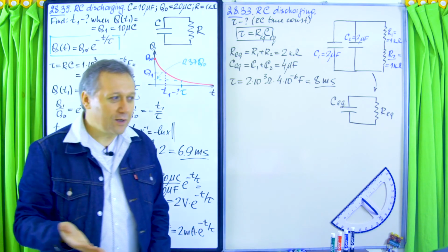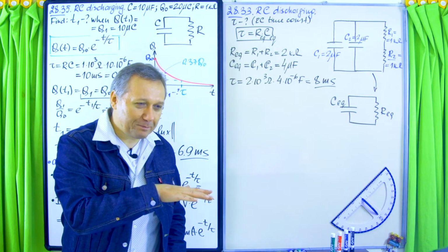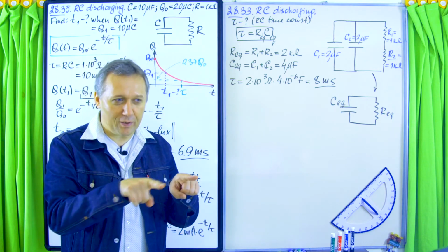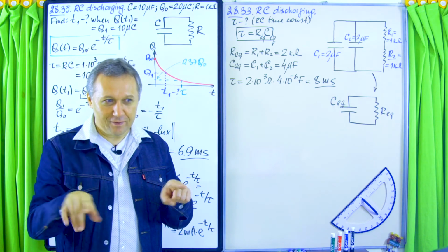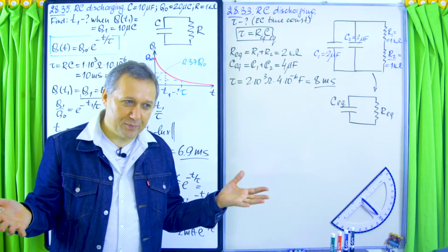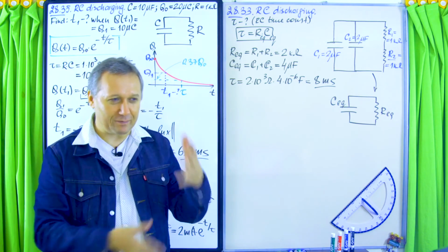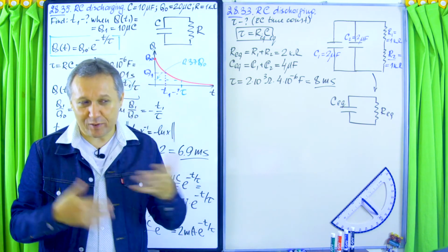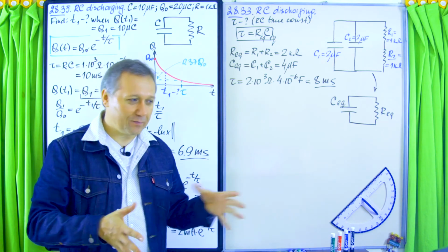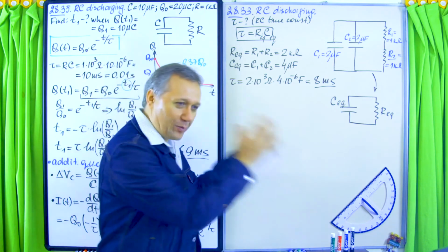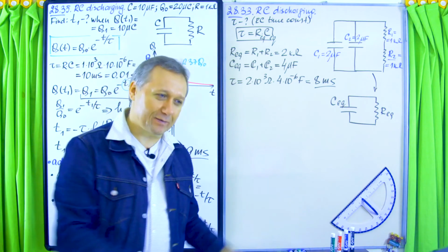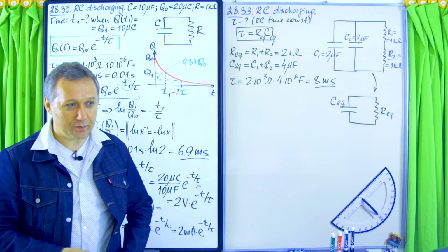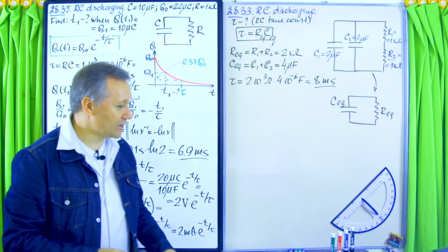And then we noticed that if you make your pulse smooth, so if you don't have square pulses, then that bistability disappeared. So I calculated the RC time constant, the one which gave me the best results, and then put it between the power supply and my laser. So this small box with an RC circuit made my pulses smooth.